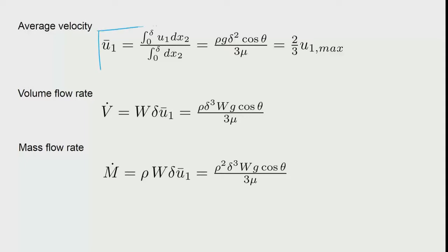So, very often these flow rates are available, and then we are required to find the average velocity, the time duration spent on the plane, and the oxygen pickup and so on. The average velocity is always defined in this manner. If we have any functional form, then you have the ratio of the integrations. The numerator will have the velocity, the denominator will not have it, and the rest should cover the entire domain. In this case the domain is 1D, so there is only one distance variable.